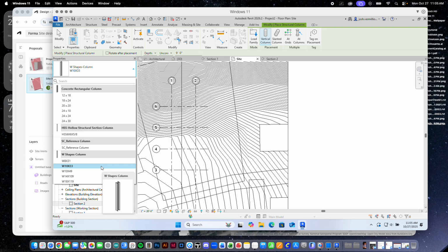You guys in structures right now? You guys been sizing steel beams and columns? Yeah. So what does a W10 by 33 mean? What are the numbers? What does the 10 mean in W10 by 33? The structural depth, right? The depth of that web, right? And what does the 33 mean? Weight per linear foot, so 33 pounds, right?